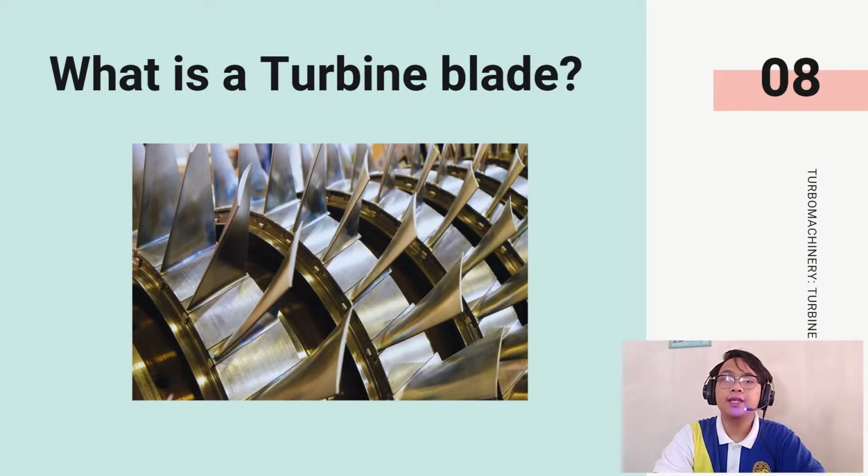The turbine blades are often the limiting component of gas turbine, in which to survive in this difficult environment, turbine blades are often made of exotic materials such as superalloys and use many different methods of cooling that can be categorized as internal and external cooling, as well as the use of thermal barrier coatings. To properly introduce turbine blade, let's watch a video about the birth of turbine blades.